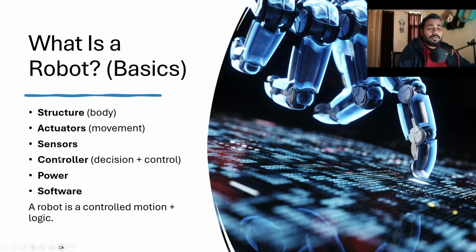And this control is one thing. We have two separate wirings going throughout the robot. One is for the control line. You can design your robots in whatever way, but I'm talking about the most basic thing. There's one separate control line that gives the signal to the machine, and then the power is usually separated from the logic. This is best practice. So for that power, we are going to use our computer SMPS for now. We will invest in a battery pack later on to keep things more modular and simpler.